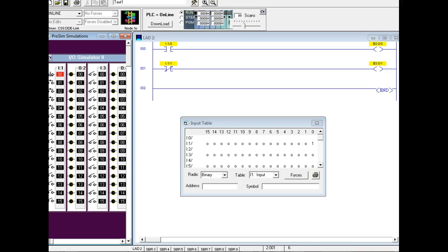So this is examine on, examine off. But what it ends up with is our symbols being, in PLC, we use a normally open symbol for all our inputs if we use examine close. Now, we're not talking about relay contacts.